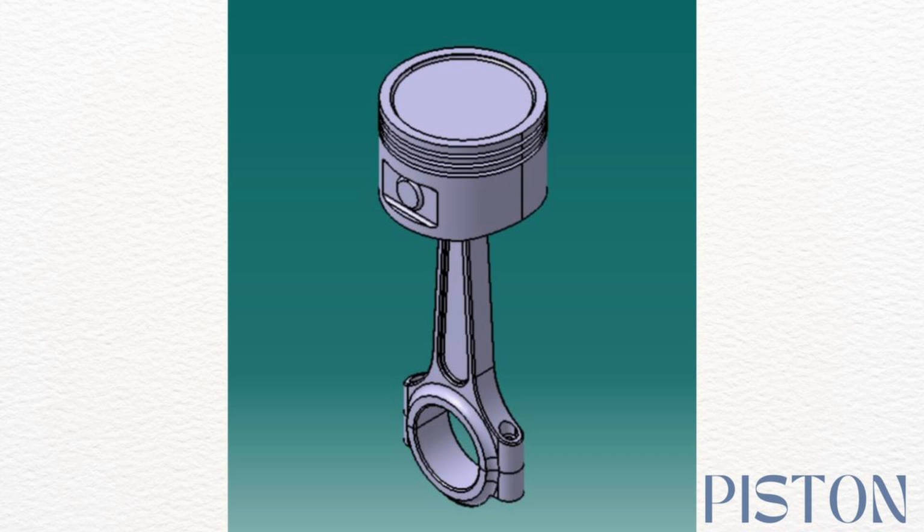The piston undergoes reciprocating motion inside a cylinder. This motion is driven by a crankshaft and connecting rod assembly, converting rotational motion into translational motion. The piston mechanism converts energy from combustion into mechanical work, which is then transferred to the crankshaft. The equation for work done is the integration of F combustion.